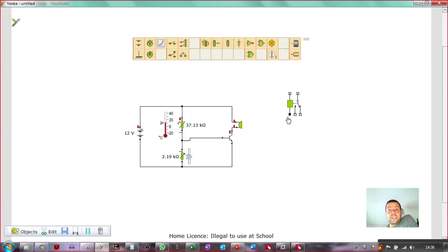Okay, so a relay is an electromagnetic device. That's basically a solenoid in there. When you pass current through it, the solenoid will either outstroke or instroke, depending on how it's set up, and change the state of that switch. Really handy. Notice the three connections in that switch are not connected to the relay coil. They are electrically isolated from the relay coil.